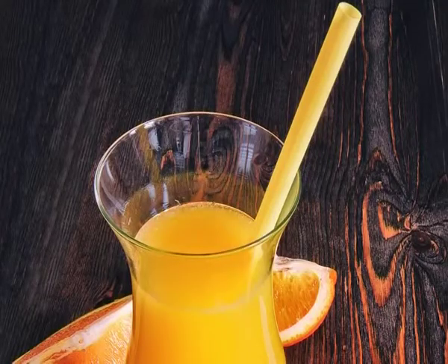First, if the flow is uniform, then all the measurable properties of the fluid are uniform throughout the cross-sectional area. These properties may vary from one cross-sectional area to another, but at the same cross-section, they are the same in the radial direction. For example, fruit juice flowing in a pipe has the same value of its properties at the center and the inside surface of the pipe.